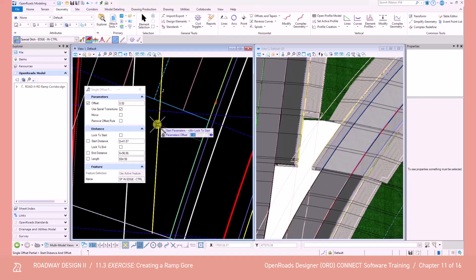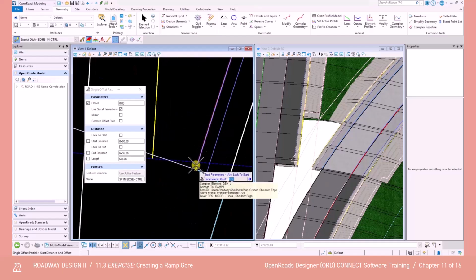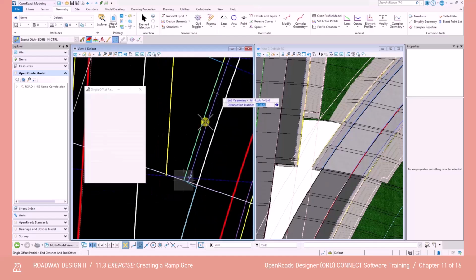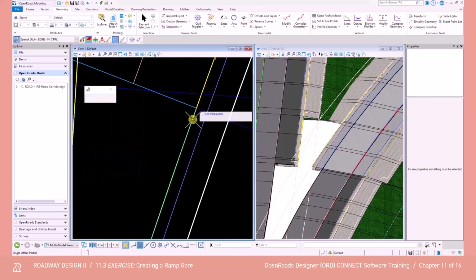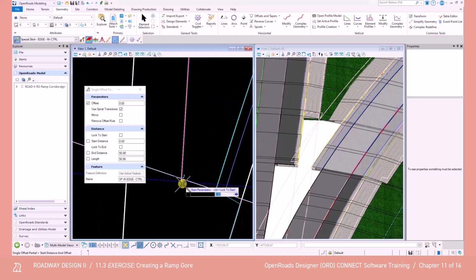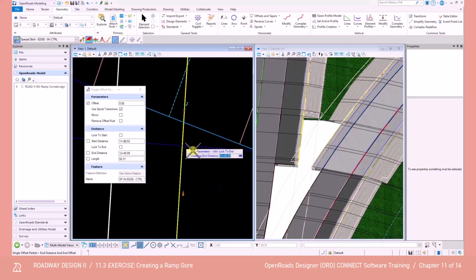We're going to start at the start of the concrete template, and then end it at the end of the parametric constraint. Then we're going to repeat that last step for the GSHR line on the mainline corridor. Once again, we're going to start it down here at this key station, and then end it up here at this key station.